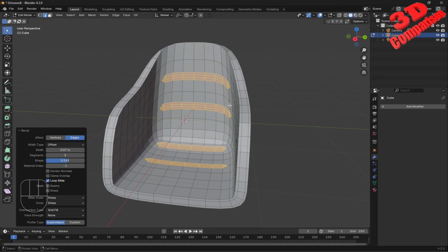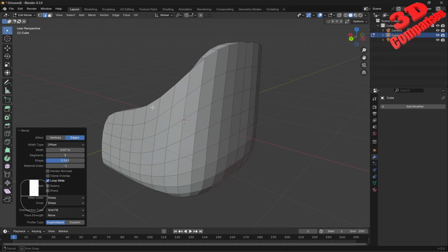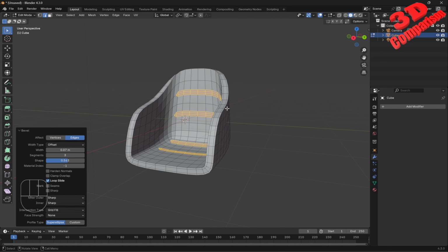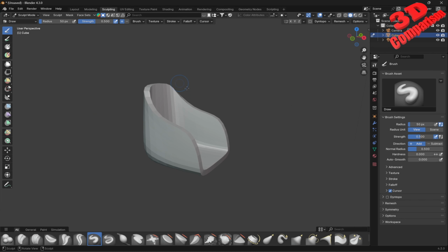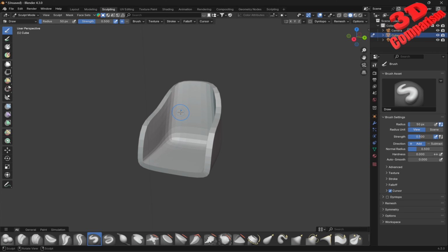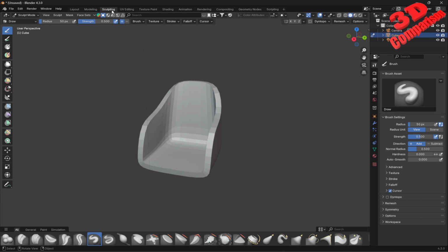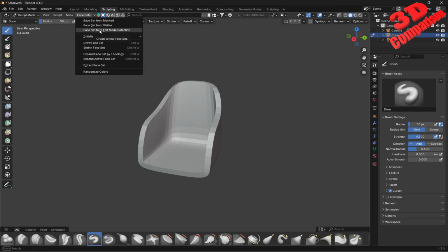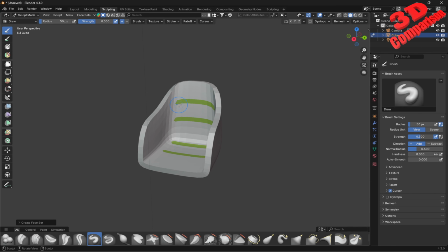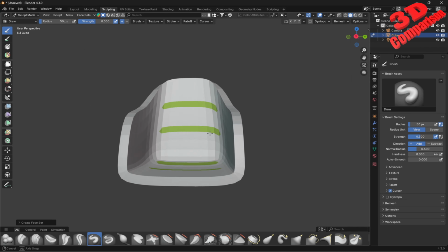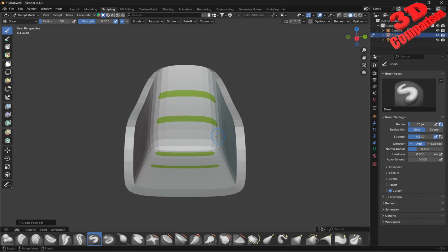Now, this will be the selection, and we can jump within sculpting in order to give the shape of this chair. So I'm going to jump within sculpting, workbench at the top. I didn't deselect because this is important. I still had that selection, and within sculpting, if I go to facets and I want to enable the facets from the edit mode, you're going to see that those will remain like that. So those will not be influenced by this cloth filter.